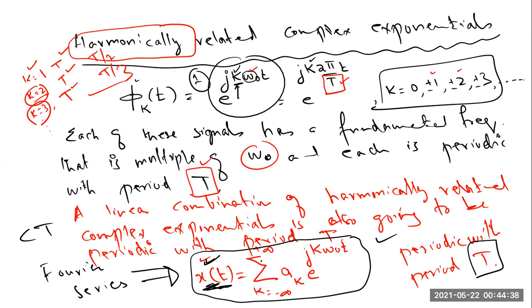So for any periodic signal, when you expand this summation operator, you will get a number of terms. You will get a constant term for k equal to 0. Then you will get the fundamental component or first harmonic component, then the second harmonic component, third harmonic component. So depending upon the value of k, this expression will give us a number of components that we call harmonic components. So for periodic signals, we always use this terminology of harmonic components for the different components present in the signal.